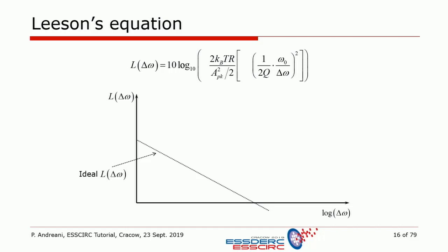which has actually three different segments. The first one, and you see here we have a noise factor F, accounts for the fact that we do not really have just the tank resistance, but also other resistances. Definitely, we are going to have the noise from the negative active resistance.